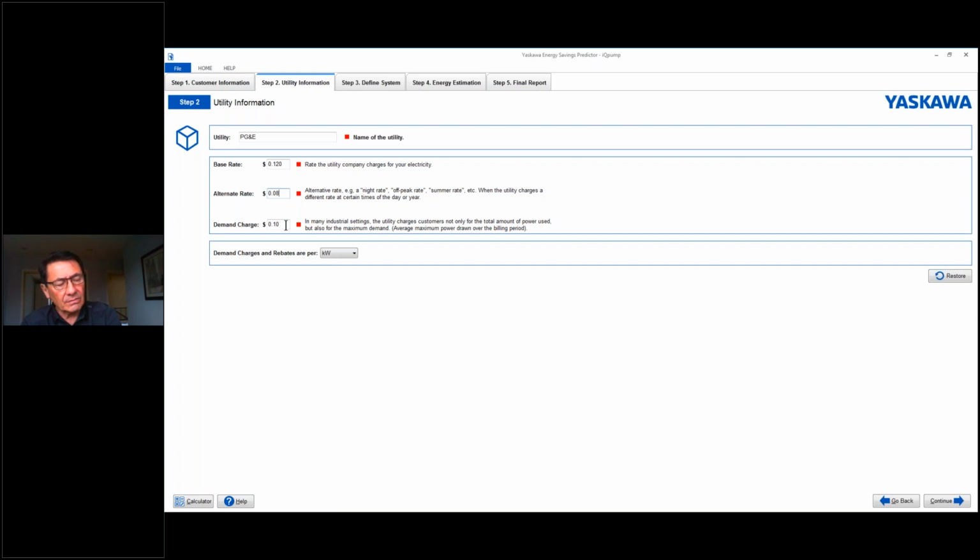When you start an electric motor with a contactor called across the line, that motor will pull up to 600% inrush current, but it'll also put a huge torque spike out into the driven equipment. Basically, think about sitting at the traffic light and flooring your accelerator. Well, for those of you that remember what manual transmissions and clutches are, your clutch is in, you floor your accelerator, and you do what we used to call pop the clutch. You just let the clutch out quickly.